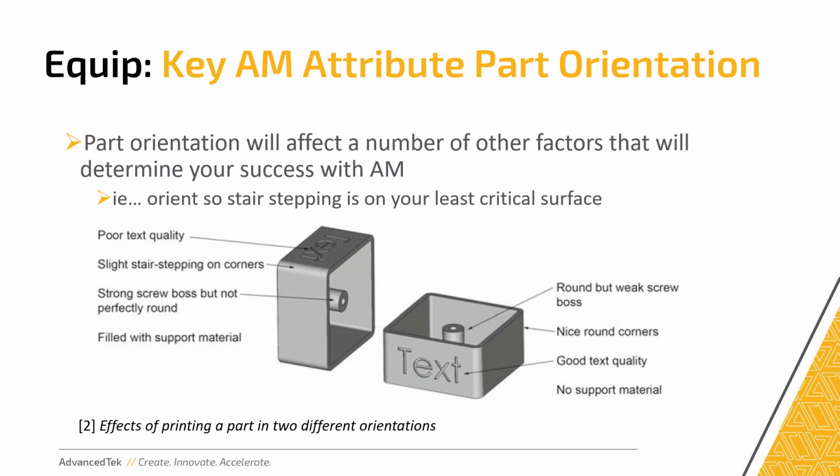On the other hand, if I build it laying flat, I'm going to have a much rounder screw boss with maybe nicer looking threads, and this might be fine if it's just a prototype. And I'm more concerned about the fit rather than the strength of someone torquing on that screw boss. I'm going to have nicer corners, some better text, no support material.